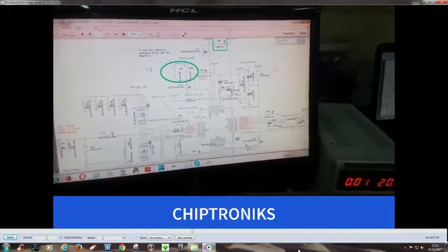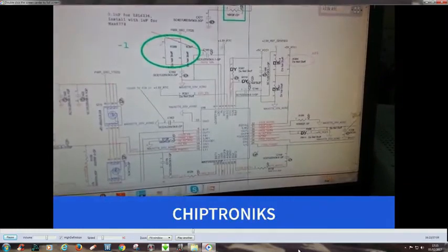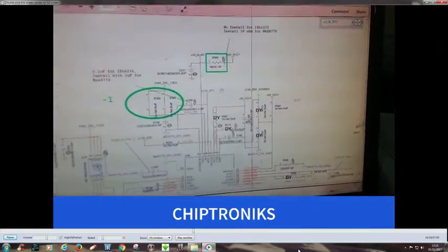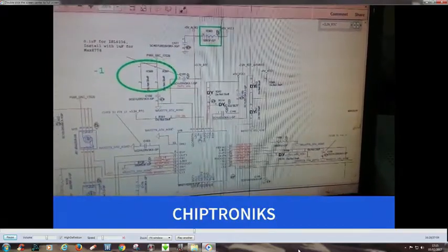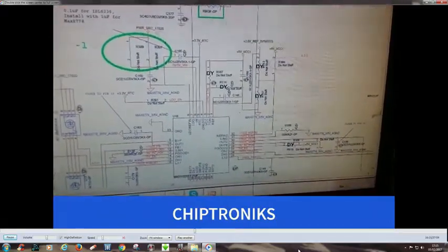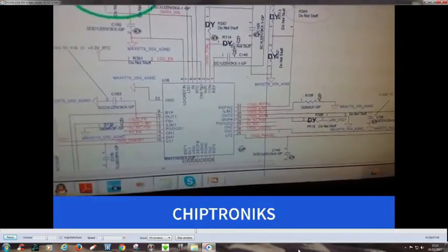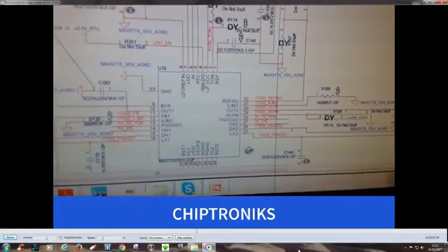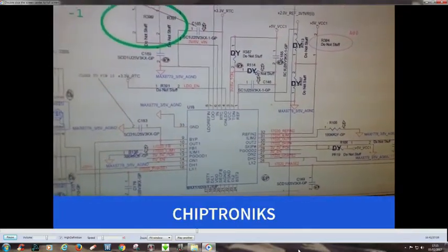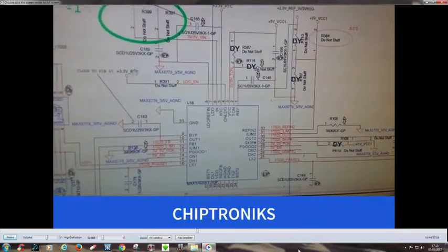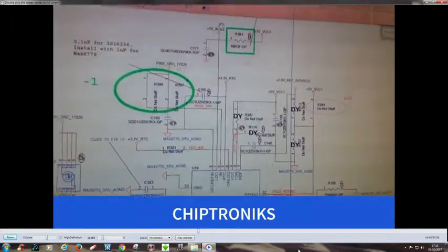So we have checked this IN and VCC. In this board you can see this VCC is actually connected with this 5 volt ALW2. So the only thing that you have to check is IN, and you can also check this on LDO. There is one special signal inside this IC. When this fourth pin gets this voltage, this 3.3 volt_RTC, then this LDO will give output 5 volt.